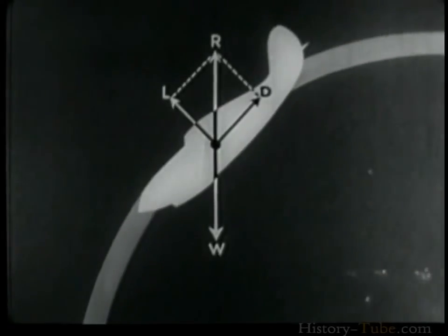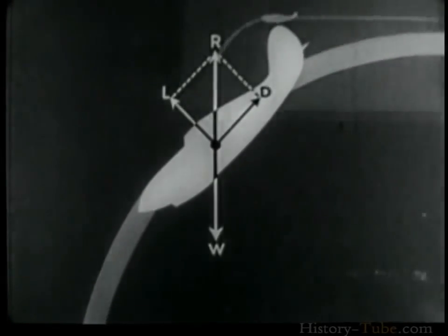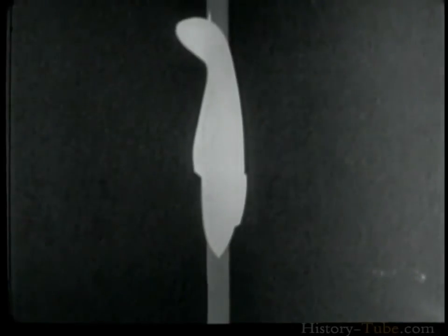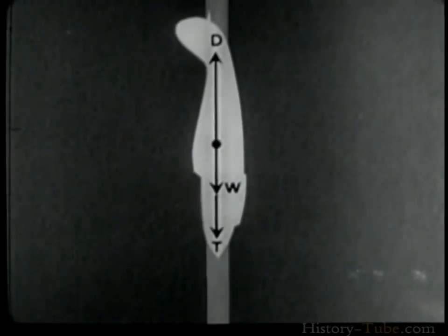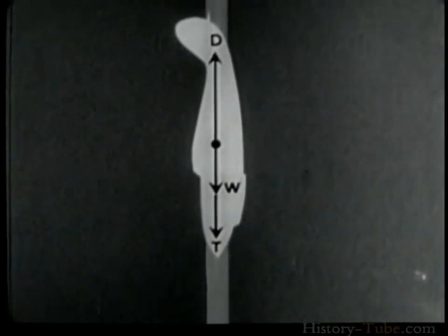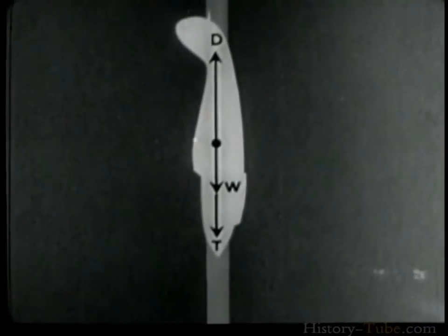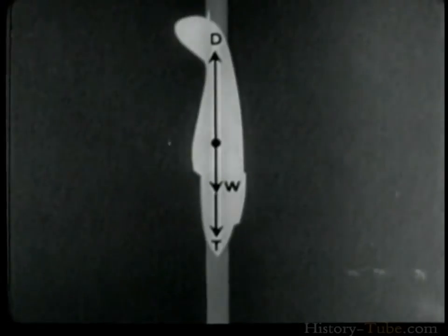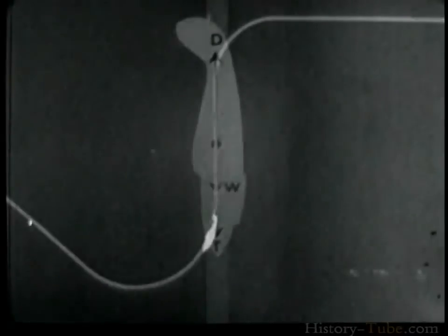Lift decreases, since in this attitude the weight of the airplane is opposed by the resultant of lift and drag. As the flight approaches the vertical, speed increases until the terminal velocity is reached in the so-called vertical dive. In this condition, lift is 0, and the weight of the airplane plus its thrusts are opposed by drag alone.